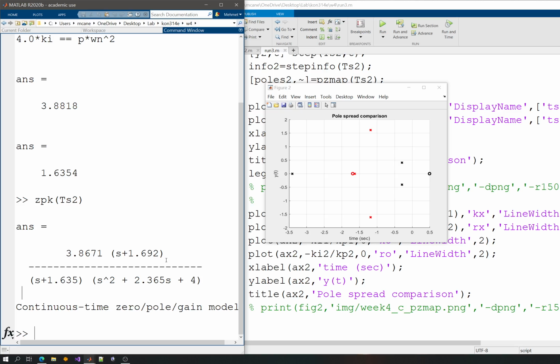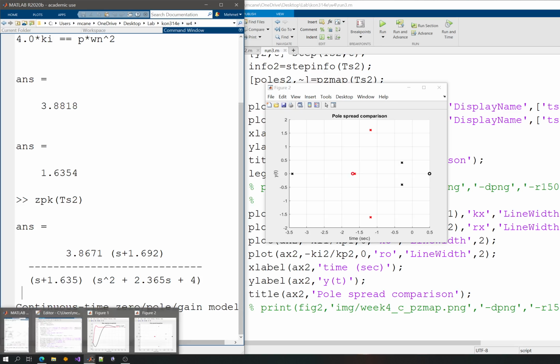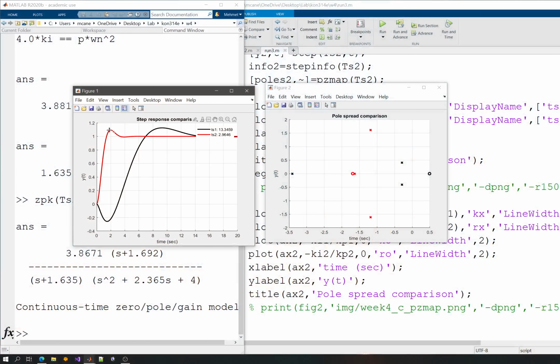So that's that. And this is also explaining why this is working better in terms of overshoot, since we said that we will have 10% overshoot, and it has approximately, what is the value here? 9.33% overshoot, which is sufficient in this case. But the other one doesn't have that, and the other one has some adverse effects in it. This is the reason why.